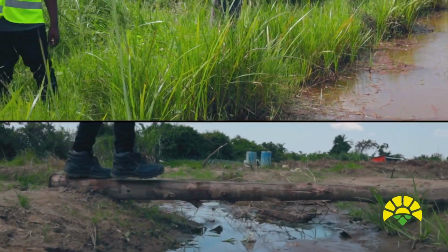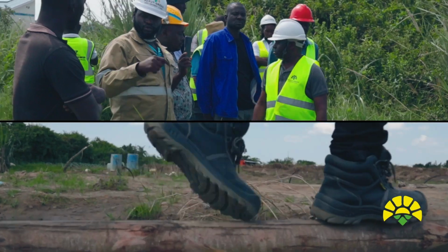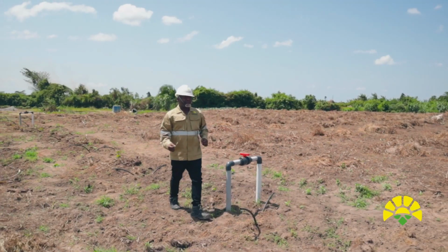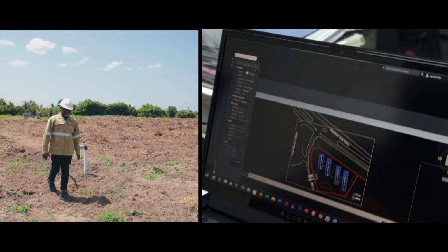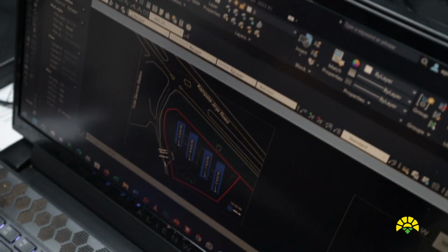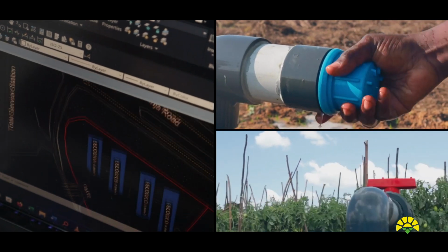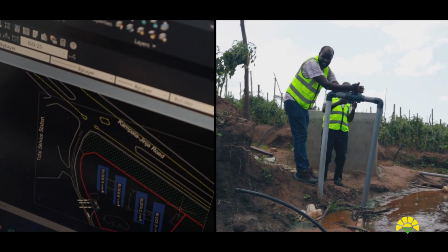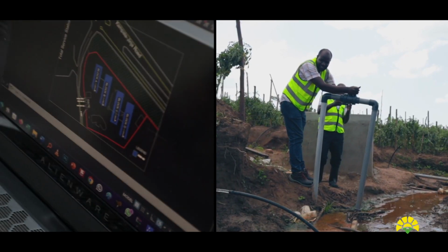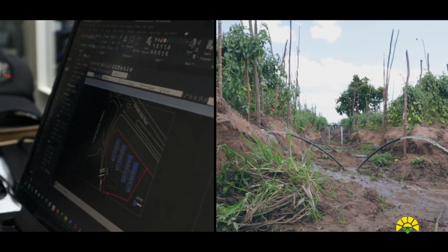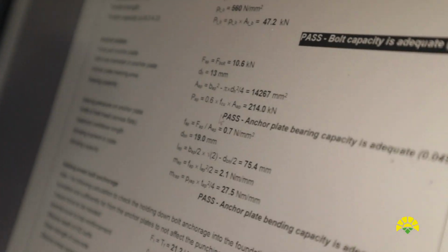This project is mainly producing water for domestic consumption, but also for agricultural use. When you have optimum designs, you'll be able to provide enough water because our crops need water, so you can actually produce crops throughout the year. We look at the demand of the different communities or villages that we are going to supply, and then we assess the supply if it is sufficient to meet the demand of these different communities. After that, we size the different components that can now make this system functional.